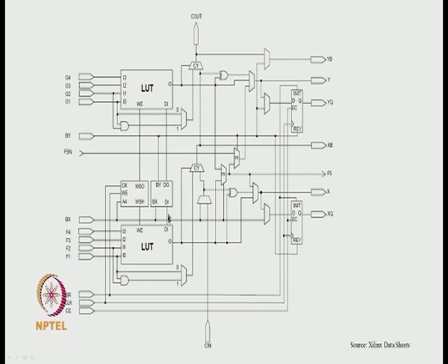This is the input to the flip flop, the D's of the flip flop. Again it is connected in a bus, and this address can be used to decode the input flip flop. So that circuit is made available so that if this lookup table is not used for logic, then it can be used as a memory.